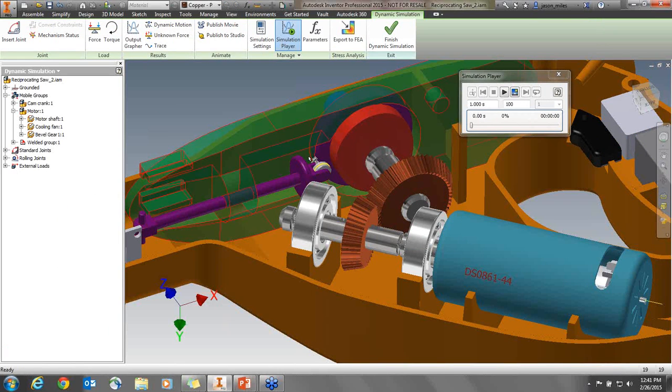It is a symmetrical part, and by default, dynamic simulation attempts to reduce symmetrical component movement. You're probably asking why, so let me give you an example. Consider a wheel assembly. You have a tire mounted to a rim, and that assembly is attached to the vehicle with lug nuts. The function of a lug nut for simulation purposes isn't to revolve around its axis. It is to constrain the assembly to the vehicle. Because the lug nut is a symmetrical component, the rotational degree of freedom is automatically removed.